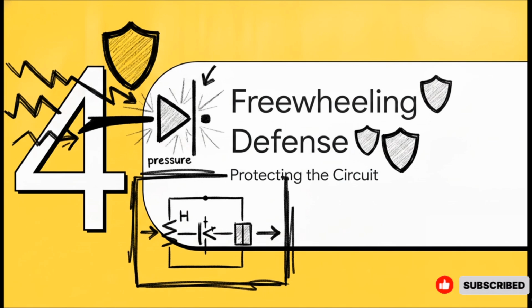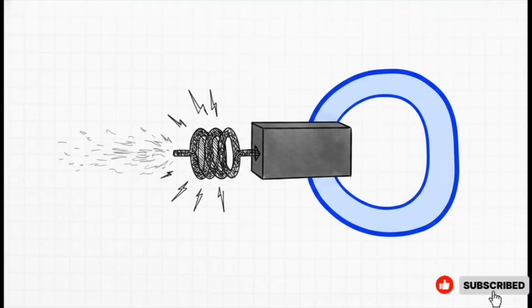Up next, Section 4, the freewheeling diode defense. All this incredible switching speed requires a seriously robust defense mechanism to prevent the buck converters from, well, completely destroying themselves under pressure. Enter the freewheeling diode. It's a protective path allowing dangerous reverse current to safely dissipate when an inductive load abruptly interrupts power.